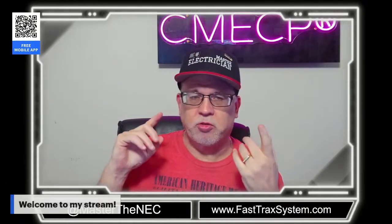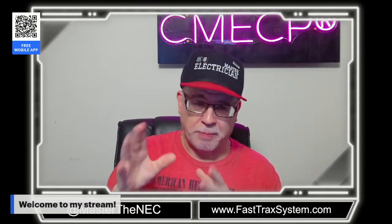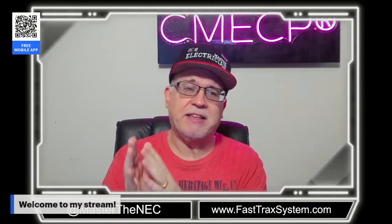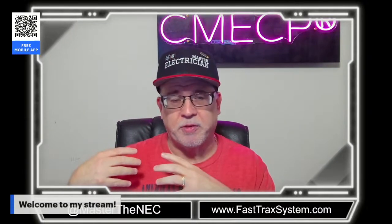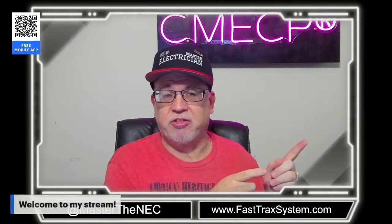So the moral of the story here is, if I'm going to use a generator for a construction site or camping, as a standalone, separately derived system, I don't need grounding electrodes for it as long as I meet those conditions. Either the equipment or the receptacles are mounted on the generator and it's a cord and plug type of application, then I don't need grounding electrodes. Okay? I don't want to use a floating neutral generator in a standalone application.